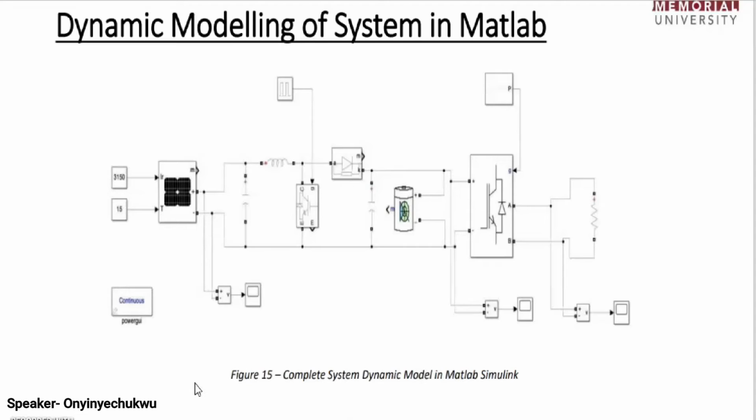A lead acid battery is connected to the inverter and also to the converter. The PV provides power to the converter. The converter converts voltage from a lower voltage to a higher voltage, so it is a boost converter, and the boost converter charges the battery. The inverter, which is connected to the battery, feeds the load, the reverse osmosis load. This system does not operate on MPPT.